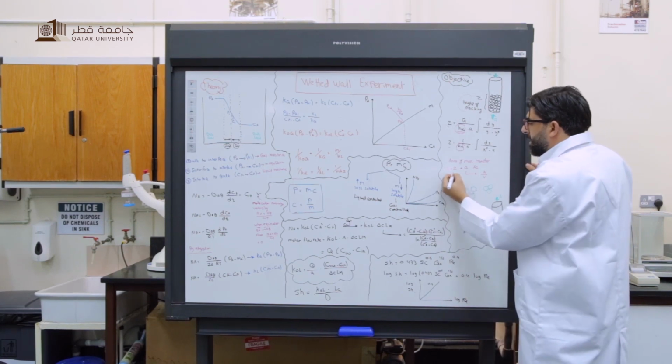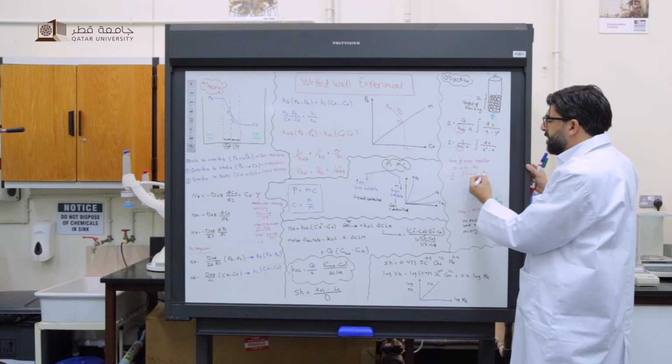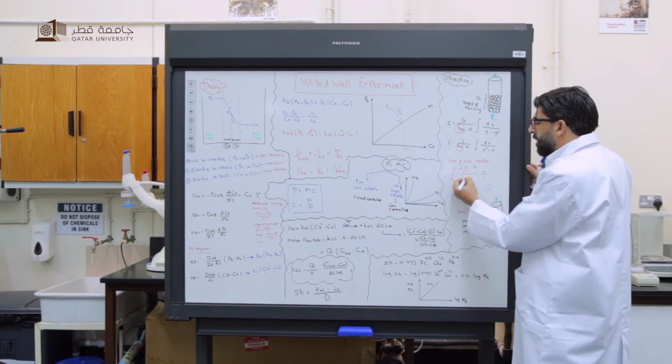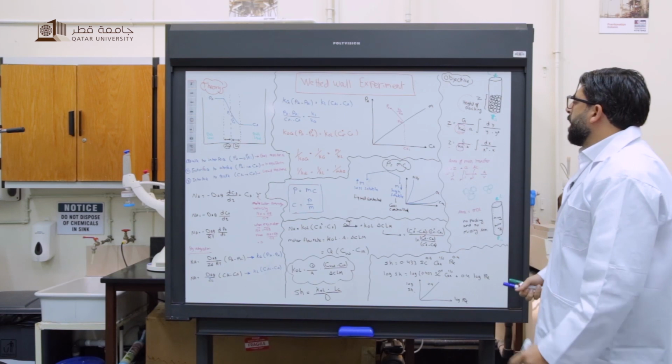Of course, Z is in meters, and A, the packing density, is the surface area of the packing over the overall volume, so it is in m^-1, and AC is the cross-sectional area in m², so this is the mass transfer area.